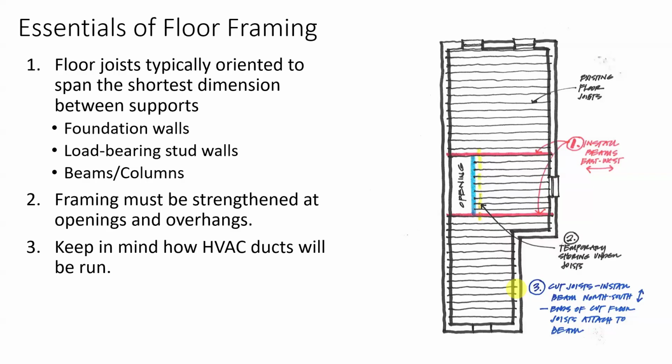So that's why typically in a house we don't blow our air in the middle of the room, because that hot air is going to rise up to the ceiling and hit the windows, cool off, and then there's going to be this constant loop of cold air running around the floor. So if you've ever been in a house where your feet are cold, that's probably what's going on. They didn't get you enough heat out at the outside wall.